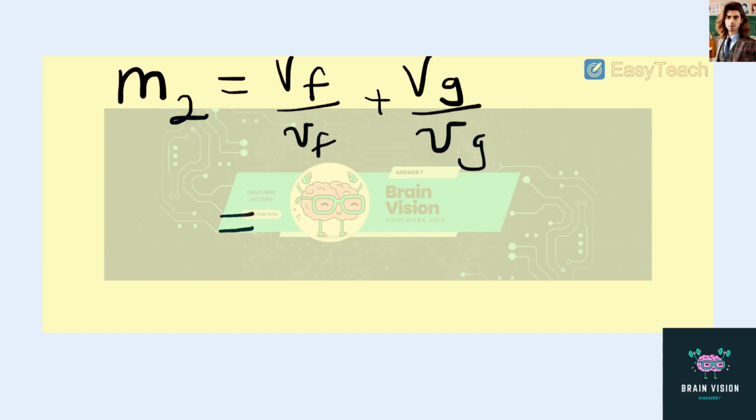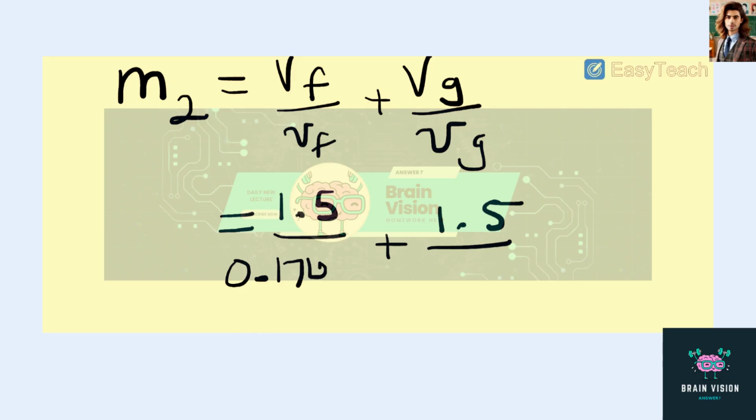And we have that condition where the valve is going to close when half the volume of the tank is liquid. So what we can say is that this is 1.5 over some quantity vf plus 1.5 over some quantity vg. Now recall that we actually solved for vf and vg from the table, and vf is 0.01745, and again vg is 6.4663.